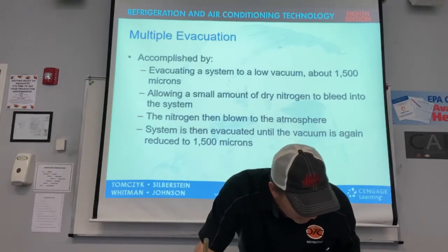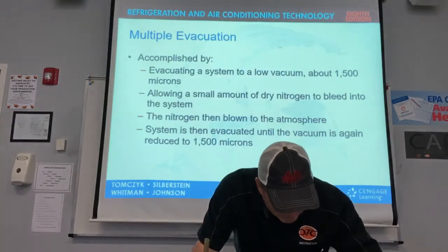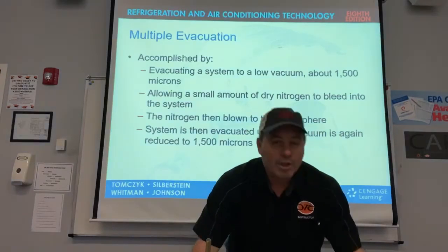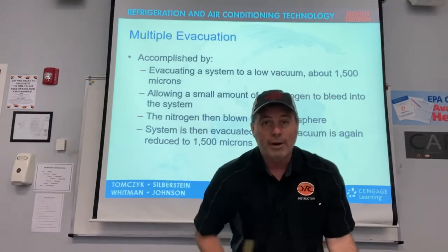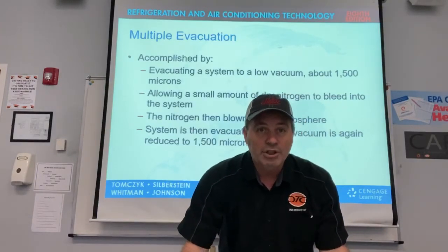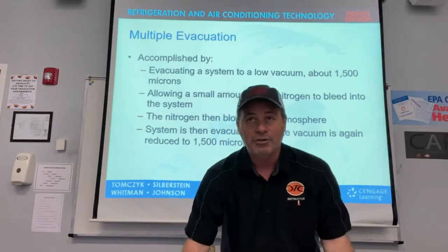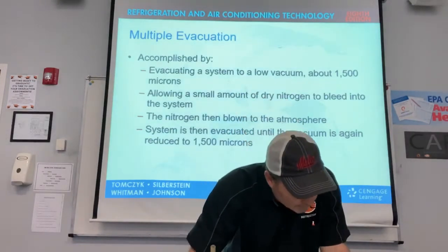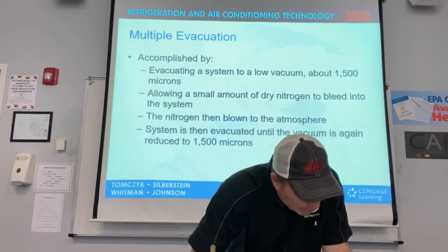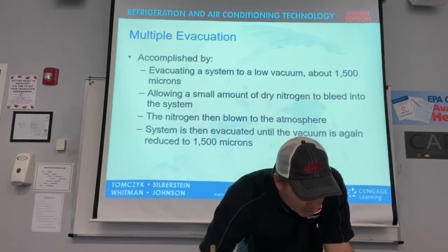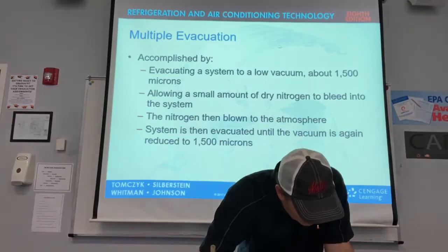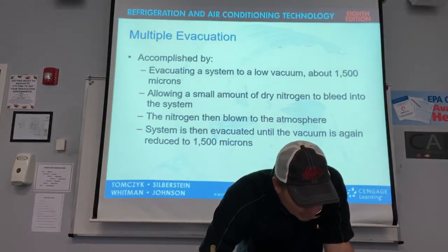Okay, so then we go to page 219 in your book. Cleaning a dirty system. Sometimes a compressor could have a burnout and it'll short. I'm going to give you handouts in the classroom on how to clean this out and the proper procedure. We know heat, refrigerant, and moisture create acid, and moisture and acid all create sludge. They do have filter dryers for burnouts, including a suction line dryer that's used to clean it out.